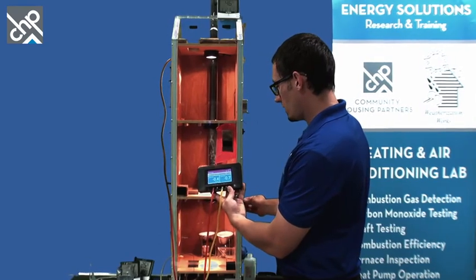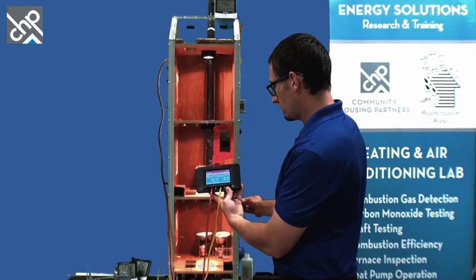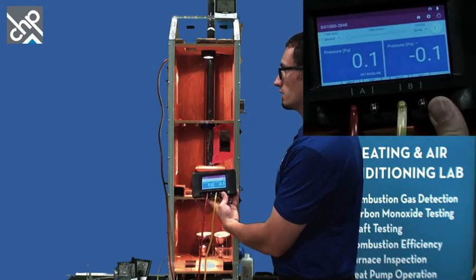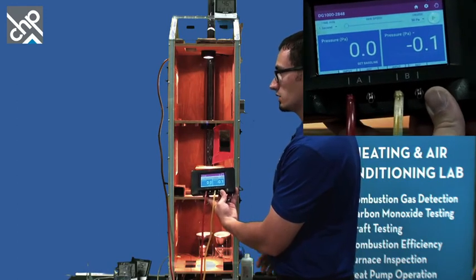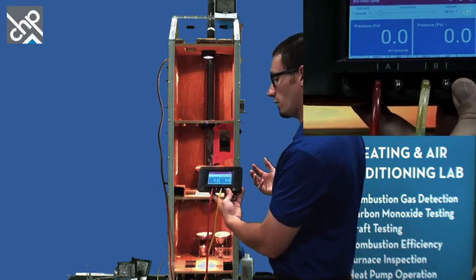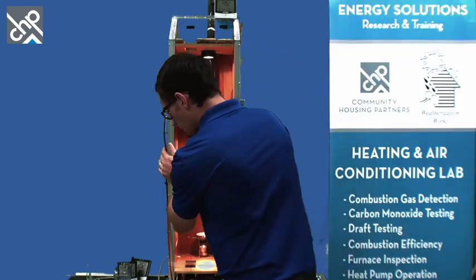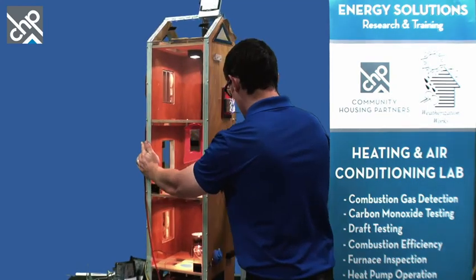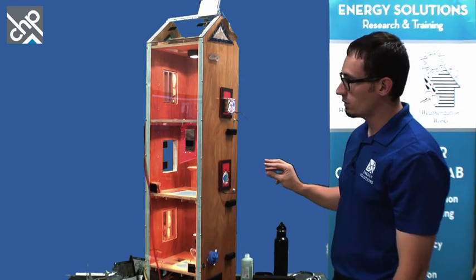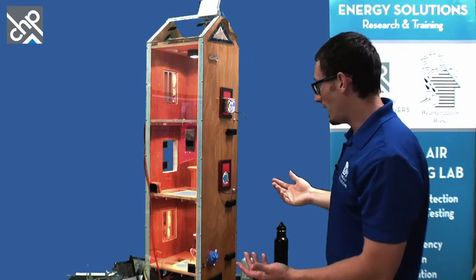I can tune this right up here. Make the pressure almost neutral in the building. You guys see that? Essentially, it's like there's no pressure being exerted on the building whatsoever. So show you guys what that looks like on the side here. This would be a pretty classic no recovery setup. So this fan is blowing air into the building. This fan is exhausting air out of the building. So it's a balanced pressure.